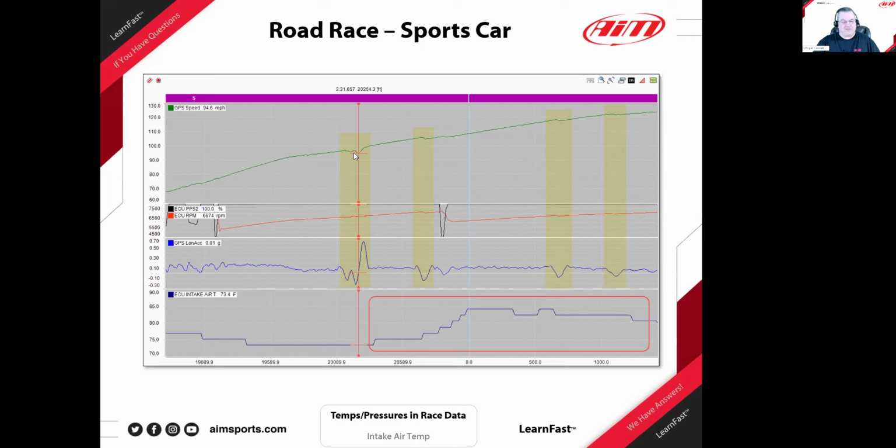And so the next thing I added was the throttle position, to see if he lifted off the throttle, and the RPM, and you can see that the car is flat to the floor. There's a shift right here, which shows for some of these back here coming off the corner. And then there's finally a shift here where the RPM drops and the throttle was off for the shift. So you can see that one there. Okay, we know the reason why for that little deviation in the speed trace climbing. But what about the other ones?